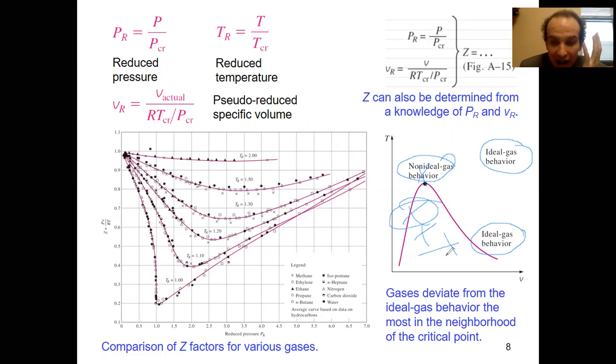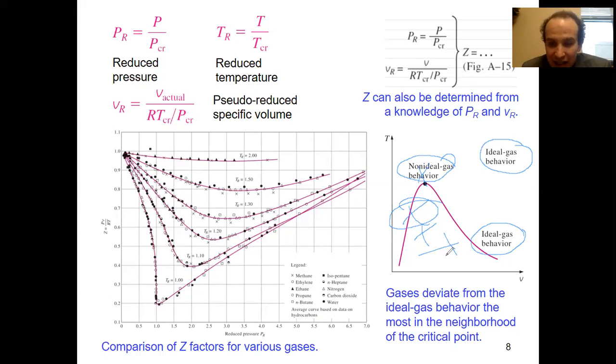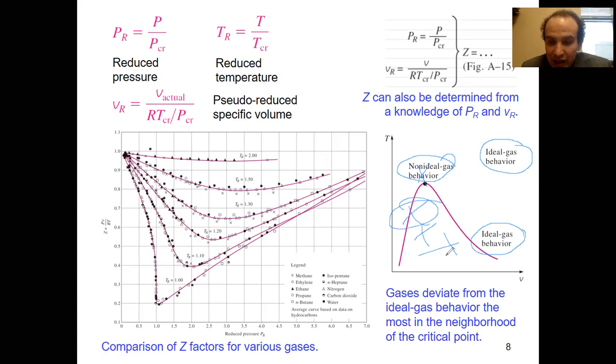We deal with ideal gas before your exam. For some of you, or those who don't attend my lectures, you think you remember the ideal gas law, so whenever you come to the exam, you employ the ideal gas law for anything. That's wrong. Most substances you deal with are not ideal gas. Water vapor is most likely not ideal gas. Freon is most likely not ideal gas. And even superheated vapor, most likely it's not ideal gas. And for sure, solid, saturated mixture, saturated liquid, compressed liquid, definitely not ideal gas.